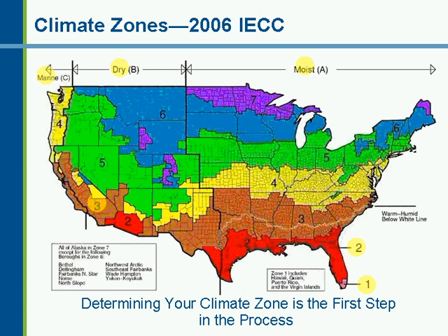Typically that's going to come into play when we get into the mechanical for economizers, and this also comes into play on some of the building thermal envelope requirements, and also things like the vapor retarder requirement. So again, this is a very significant change. And these climate zones, the identical ones, are used both in the 2006 IECC and also in ASHRAE 90.1 2004.